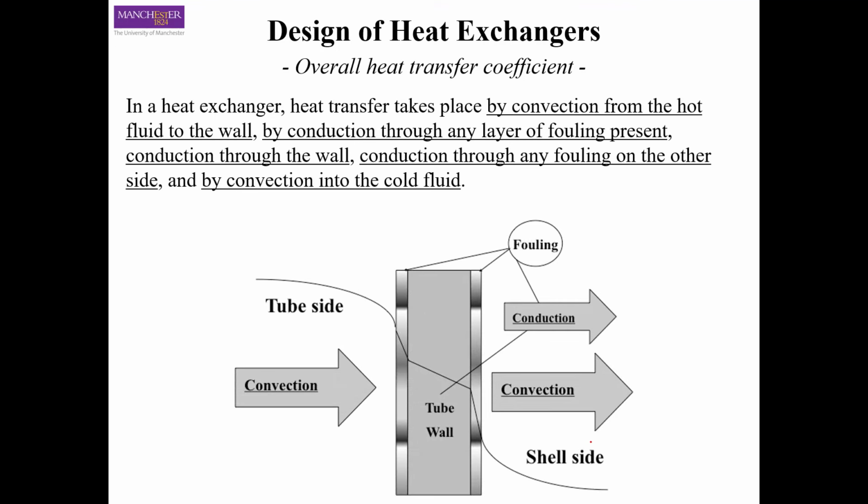So now let's look at what can be the situation. We are looking at the heat exchange, and as I said, the main heat exchange is around the tube. So let's say you have this tube again, and around the tube, this is the shell part. So this is the surface of the tube. If you look at the surface of the tube here, you will see that on the inside of the tube you have, let's say, a hot fluid. Inside the tube here you have convection as well, because the fluid is moving.